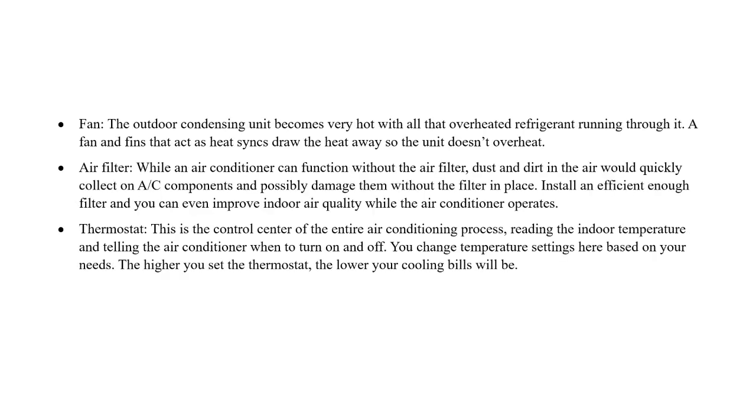Fan. The outdoor condensing unit becomes very hot with all that overheated refrigerant running through it. A fan and fins that act as heat sinks draw the heat away so the unit doesn't overheat. Air filter. While an air conditioner can function without the air filter, dust and dirt in the air would quickly collect on AC components and possibly damage them without the filter in place. Install an efficient enough filter and you can even improve indoor air quality while the air conditioner operates.